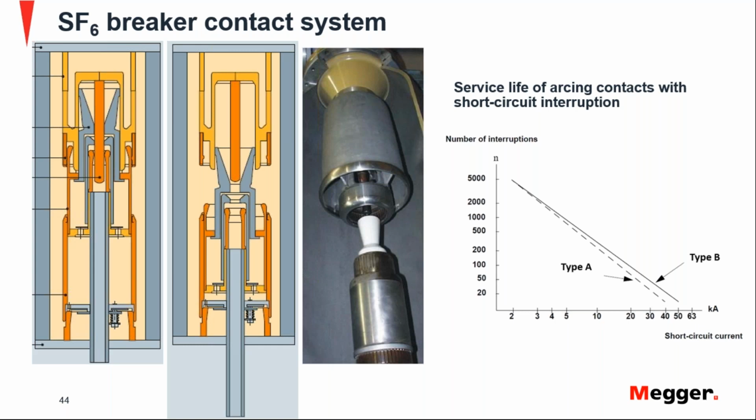Every time a circuit breaker operates under load and under fault conditions, when the contact opens, there's an arc. That arc is extinguished by the combination of three things. One is the speed of the breaker, second, the crossing through zero of the current, and a refrigeration that comes from the insulating medium. But the arc still happens, and the idea with this arcing contact is that the main contact doesn't suffer from that and doesn't get deteriorated.